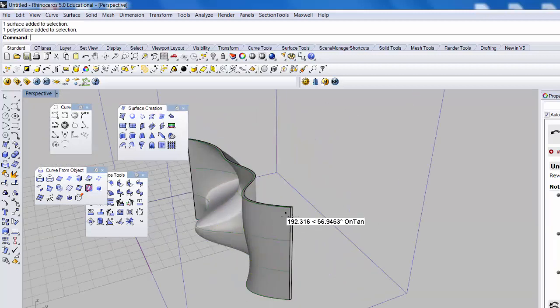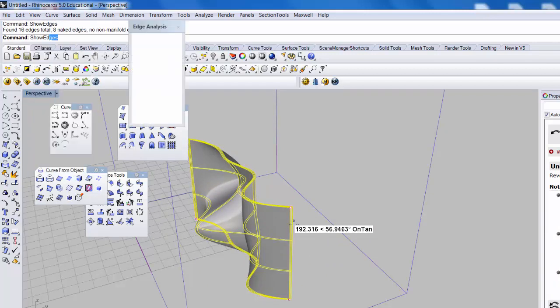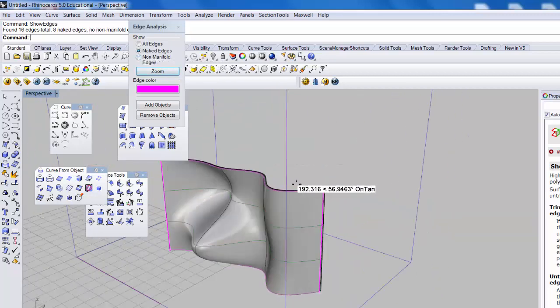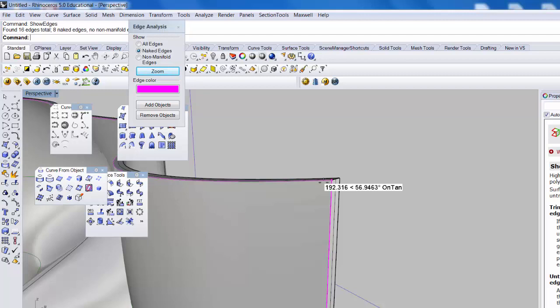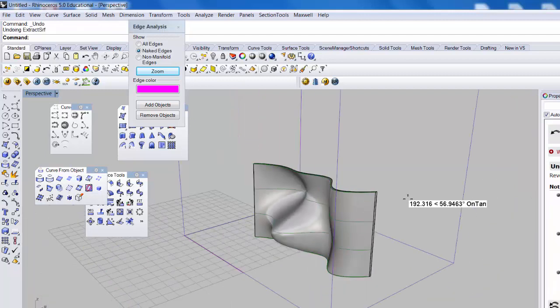These are two objects. So now if I select both those objects and I type show edges, that's a naked edge that I've made. Right? So that's showing me that I'm not a chocolate bunny anymore. I'm a chocolate bunny that my seam will let water in if I was to be submerged in water. Or if I had water inside me as a chocolate bunny, my water would ooze out of me. So we don't want that. I think it might even work still, potentially, but bad things can happen on the 3D printer with that.